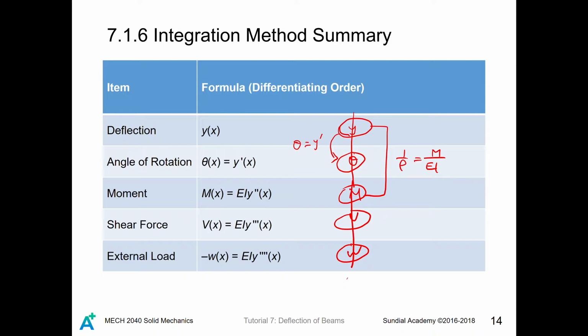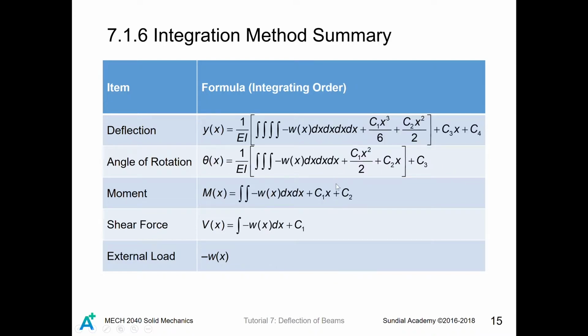The same for moment, shear force, and w, the external load, they are connected by some derivatives like V equals dM/dx, w equals minus dV/dx. So in differentiating order, it looks like this, and in the integrating order, it looks like this.